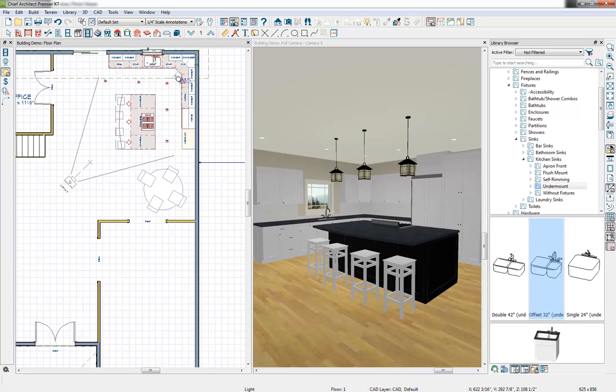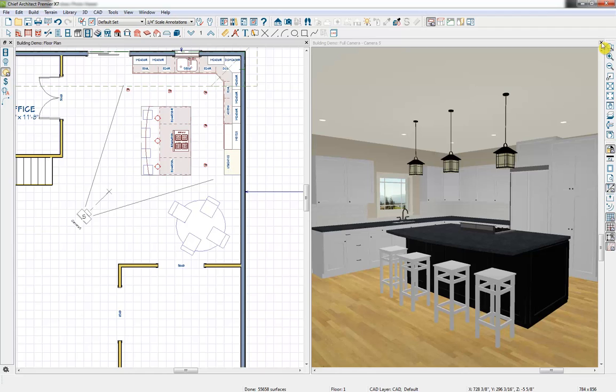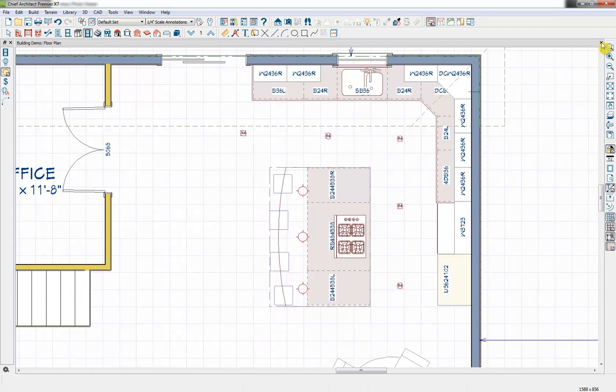And then we can get into some more electrical information. I'm just going to close out of our 3D view and focus on our 2D view and get into our outlets. You can just drop in your different outlets that you need to and place those accordingly. Drop in a few switches, so I'll just drop in a switch here and use your Connect Electrical to create your electrical plan. So very quick and easy to modify and create the plans that you need to.